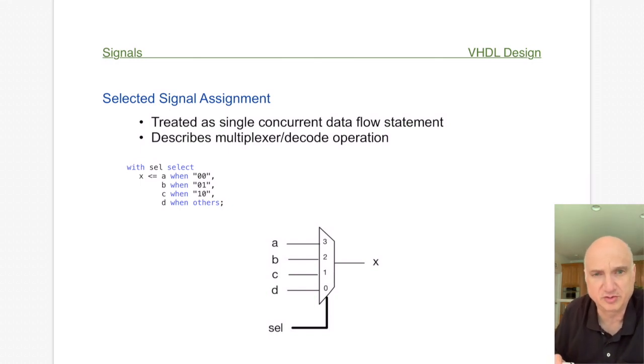It is incredibly powerful, and the synthesis engines and simulators find it very easy to generate the code for this. So it's very quick as far as turnover from logic into hardware. It's a very efficient way of generating fairly simple combinational logic, but it covers a wider range of things than you can imagine.